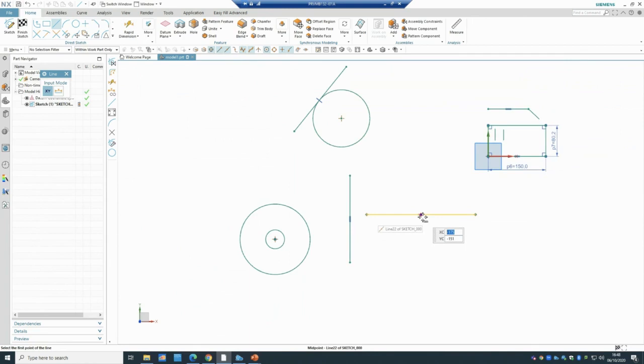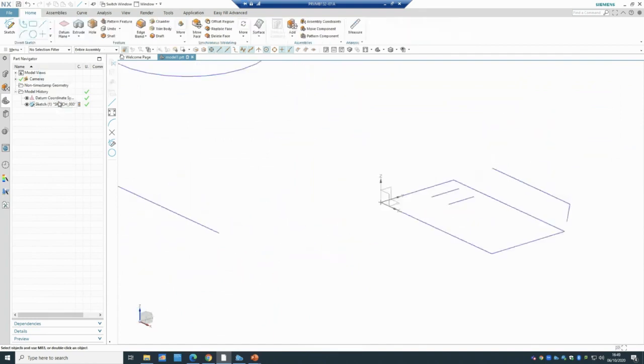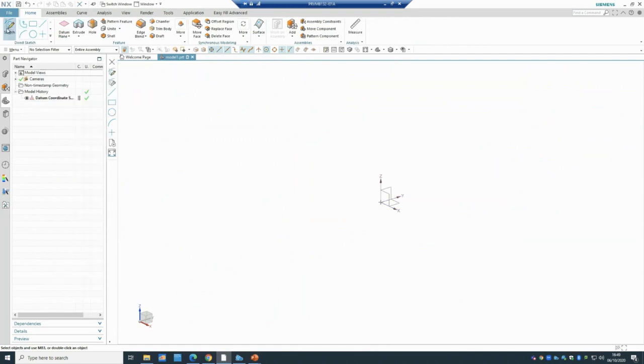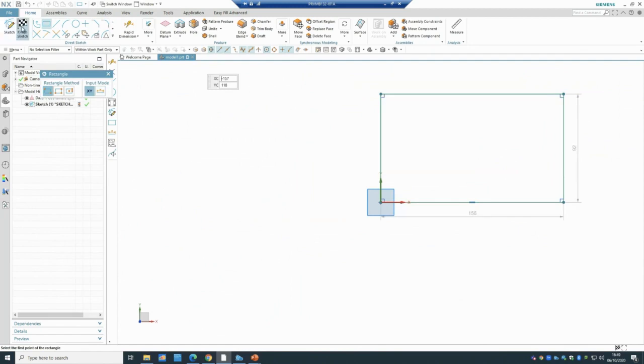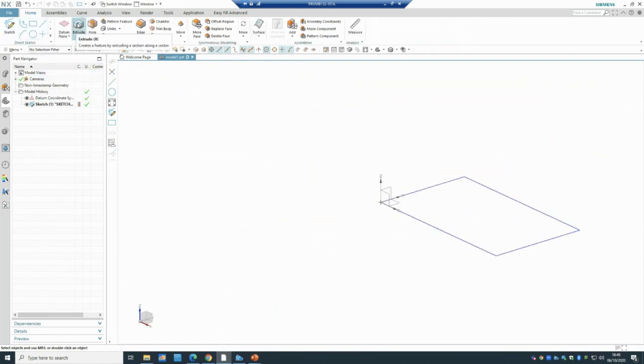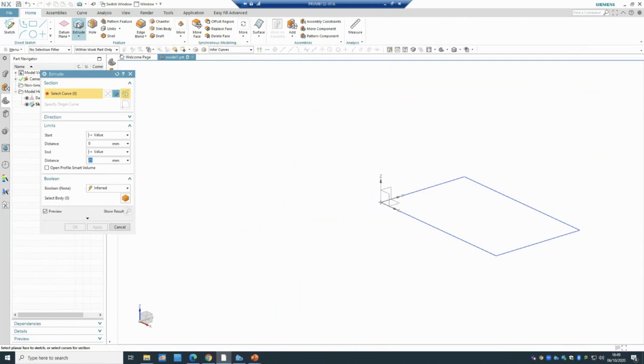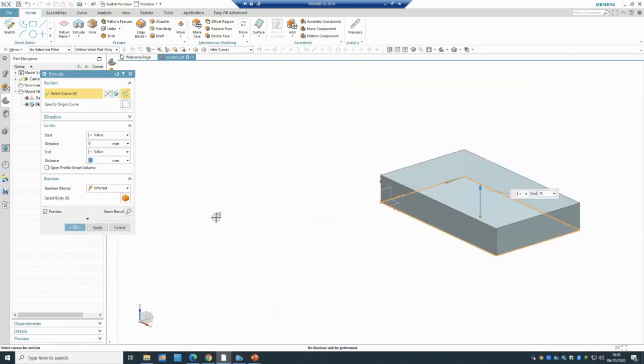Great, so we've done the dimensioning, we've talked about the constraints and also the difference between over constraints and under constraints. So let's now talk about the feature that we used last time, that's extrude. Let me get rid of that sketch. I'm going to create another sketch with a normal rectangle. And for extrude, even in SolidWorks, the people who are familiar with it call it extrude. You have to just choose a closed curve. So just choose this one, and you can see it also appears for me.